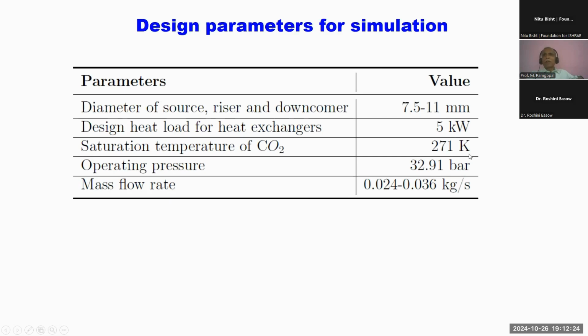And for the reasons of avoiding frost, we thought that we would operate the carbon dioxide at 2 degrees centigrade. That means the cold storage is essentially for storing fresh food. The reason why we chose a temperature above 0 degrees centigrade is that we wanted to avoid frost formation on the carbon dioxide evaporator, because once the frost forms, the simulation becomes complicated. We wanted to avoid at least the simulation complications, so we considered temperatures above 0 degrees centigrade.